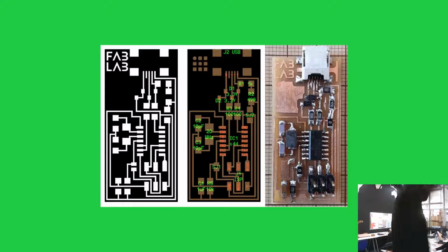And all the communication protocols depend on time. So you put a clock here. And why don't you put it inside? Well, because they say let the guys customize and make it as they want. Maybe someone wants a car which is faster, slower, cheaper. You would also need a few other things, for example, if I'm right, two diodes here to prevent the flow, and two pull-ups here. So basically, you need a bunch of components around which are not inside the chip, just so you can customize and do more things with the chip. If they put them inside, the chip would be a little more expensive, and you would be able to fit it to fewer applications.